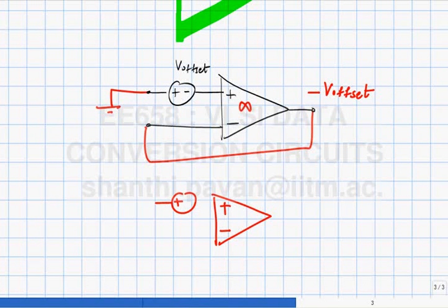So this is the original amplifier with offset. What we want is to insert a voltage like this, which is equivalent to inserting the inherent offset of the amplifier. If you knew the offset, then if you put a battery also exactly of value V offset in the other input, then the total input offset would be 0. Does that make sense?